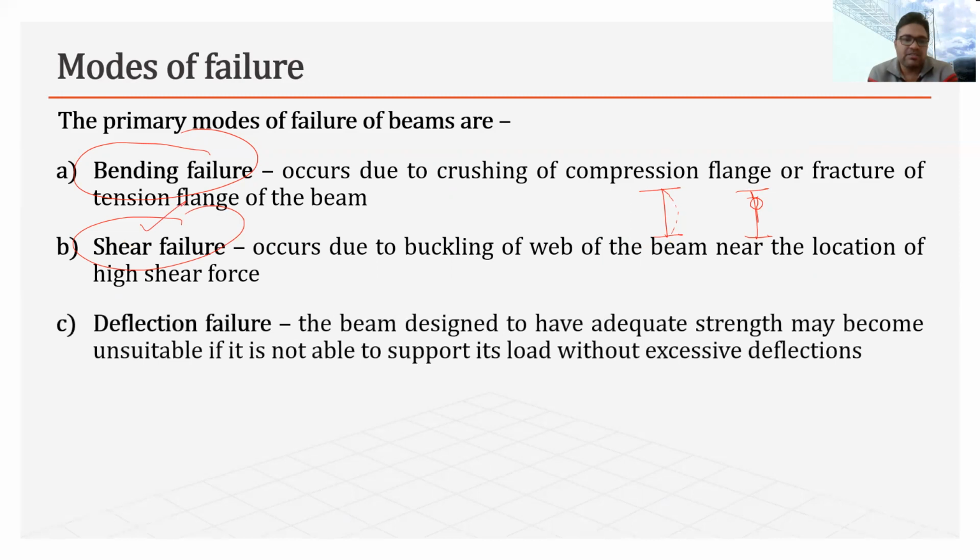And deflection failure. Deflection failure is again related to the bending failure. Sometimes the beam may carry the required load, but at the cost of higher deflection. So the IS code has specified deflection criteria also. As per table 6, we will follow the deflection criteria.